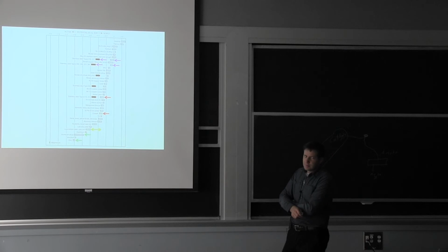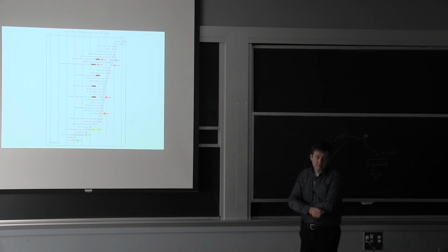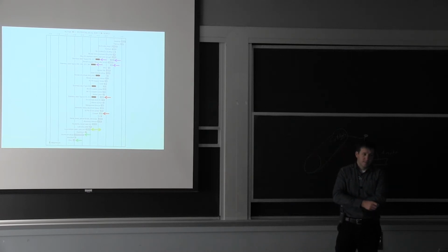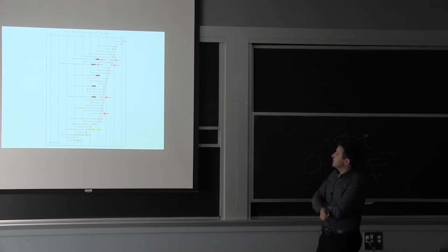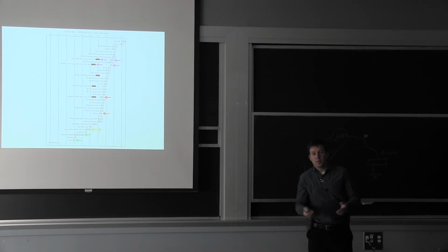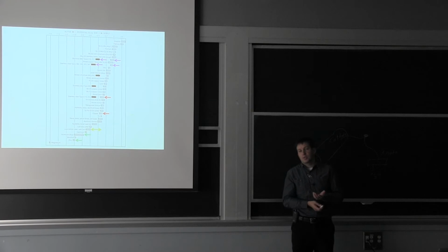Are there coating methods where you can get a single layer of graphite on something that aren't expensive? Boy, I don't know. I think graphite is fairly soft. I would worry about it as being my protective layer. We use chrome, right? You don't need to go that crazy, and we know what the issues are even with chrome, which is very ductile. Even though it's very ductile, you can have just a little area where the electrolyte's going to penetrate, and then you have pitting.